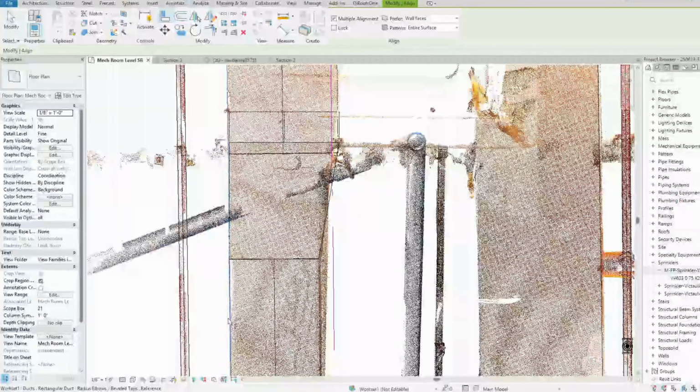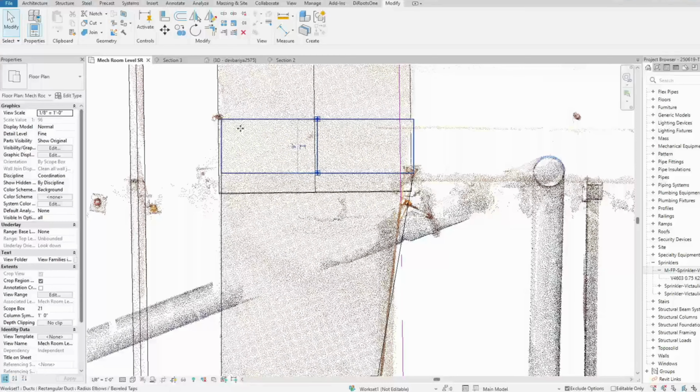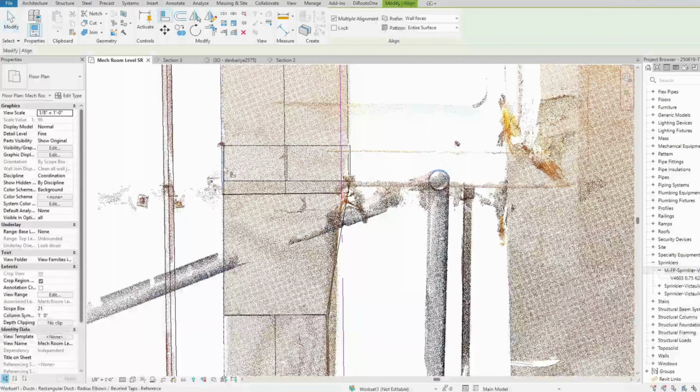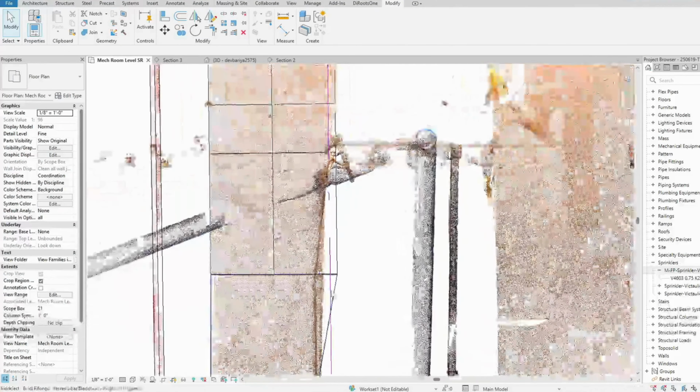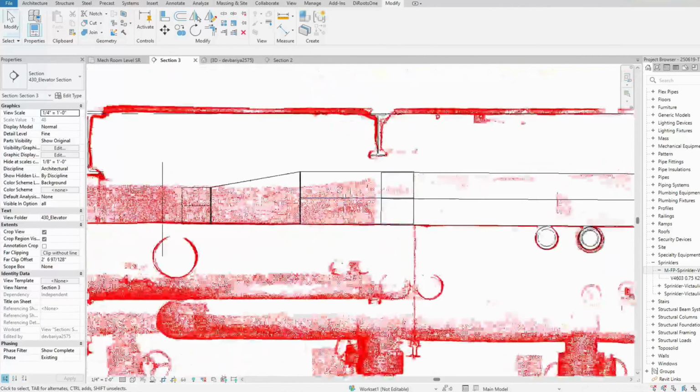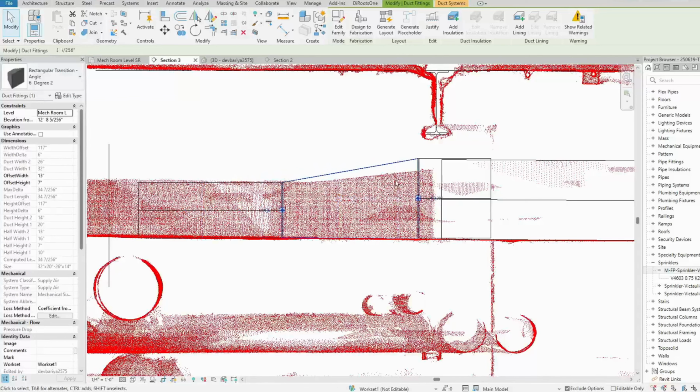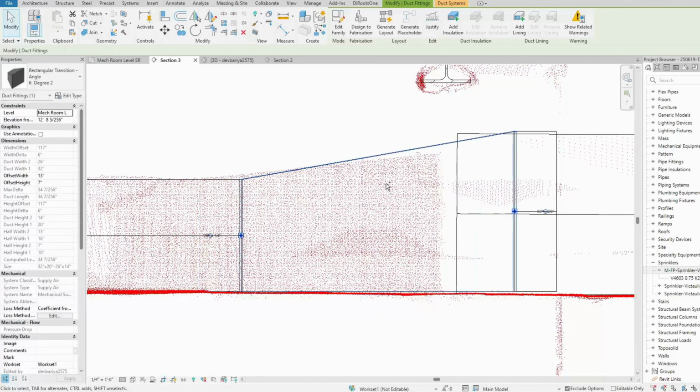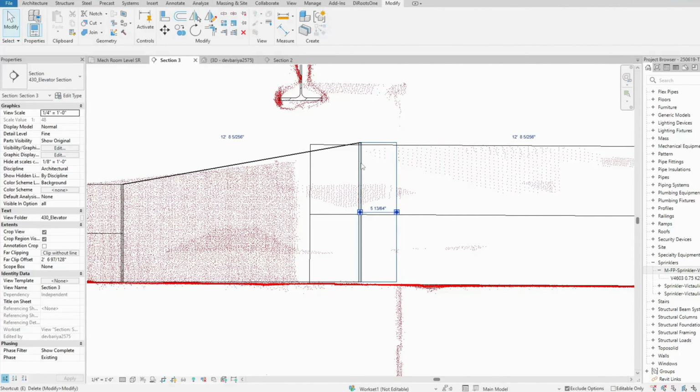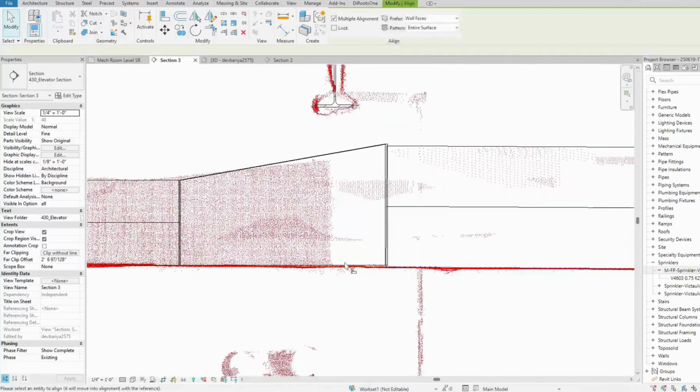You'll also see a value for flow. This tells you how much air is moving through the duct, usually measured in liters per second, L/S, or cubic feet per minute, CFM. This is especially helpful if you're doing airflow calculations or using tools to size your system properly. Next, look for the offset. This shows how high the duct is from the current level or floor. For example, if the offset is set to 2,700 mm, that means the duct is 2.7 meters above the floor.